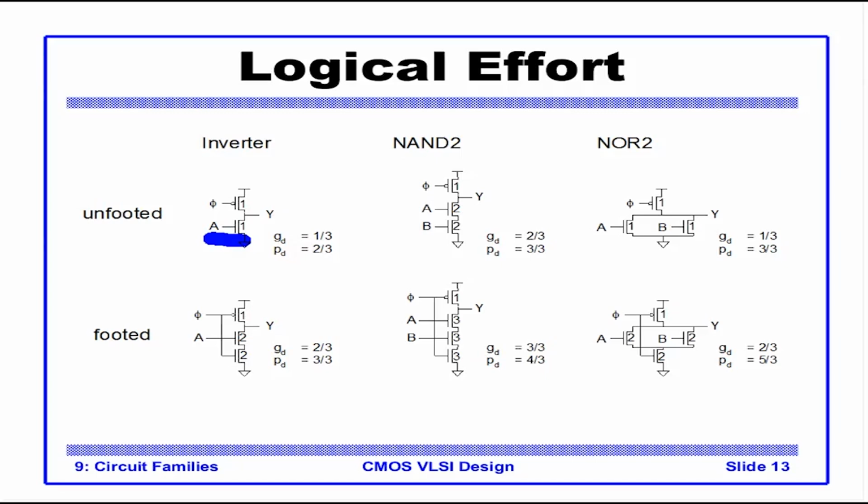So what did dynamic logic do? Dynamic logic, in fact, used a similar concept as pseudo NMOS by realizing the logic function only by the pull down network. It does not use the PMOS pull up network. So in fact, sorry, I was wrong earlier.